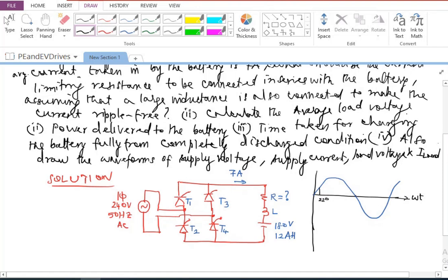So when I look at the rectified voltage or during the negative half cycle, this is how it will be. Again, let me show this is pi plus 22 or 180 plus 22 degrees. It will be 202 degrees. So let us say this is 202 degrees. And this is pi. So what we are looking at is the voltage. If I assume continuous conduction, the voltage that comes out on the output side is going to be somewhat like this.